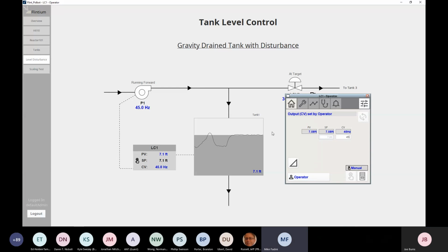And I also have a question along those lines. We have someone who has an application where the feedback from the system is delayed by about 10 seconds, a chemical dosing point far away from the control point. Can they still use PID control, or should they use an alternate type of control? Yes, it's definitely still a dead time. It's a little bit different in that it's in your measurement, but it's still part of the process as we've defined it. So the answer is yes, you can absolutely use a PID controller.